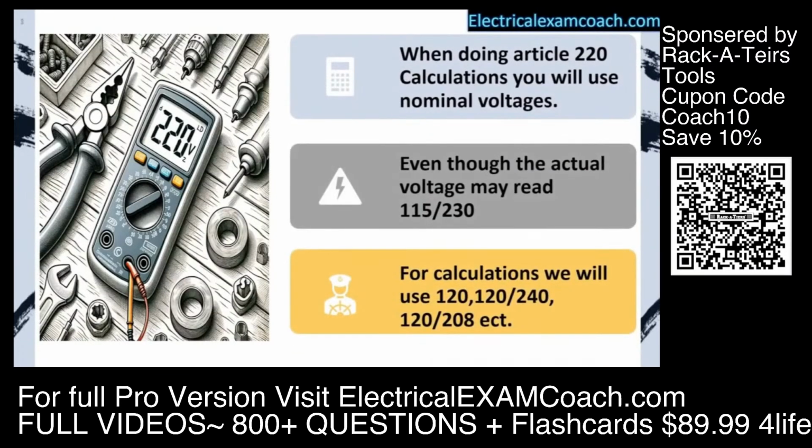When doing Article 220 load calculations, we're going to be using nominal voltages. Although our actual meter reading might be 115 or 130, for our calculations, we're going to be using nominal system voltages like 120, 120/240, 120/208. It makes it a lot easier to do these calculations, not having to guess or wonder what the actual voltage